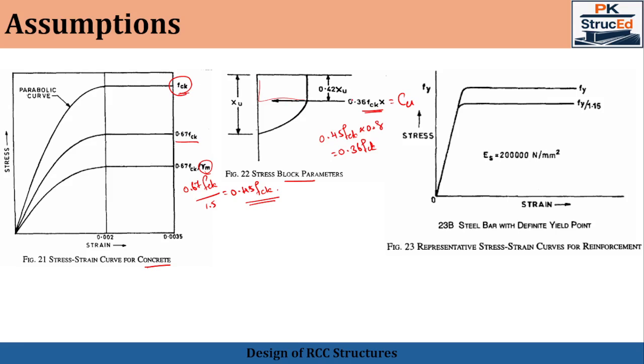And here the 0.36 gives the magnitude of the compressive force, and 0.42 Xu gives the location of that force. So both are essential for calculating the moment of resistance. Now moving on to figure number 23, which represents the stress strain curves for the reinforcement.